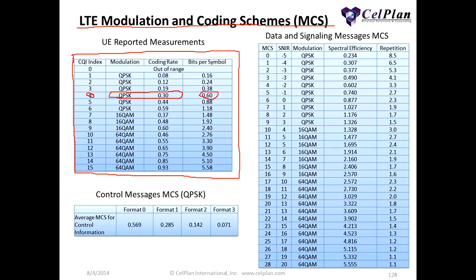Well, the eNB receives those measurements periodically, and of course those measurements are eating bandwidth. It analyzes the measurement, and it may consider it or not. The eNB has full control, because as you saw in webinar number 4, those measurements on the UE are not very precise. They have absolute variations of plus or minus 8 dBs and relative variation of plus or minus 4 dBs. So really, it is an indication, but it's a very gross indication.